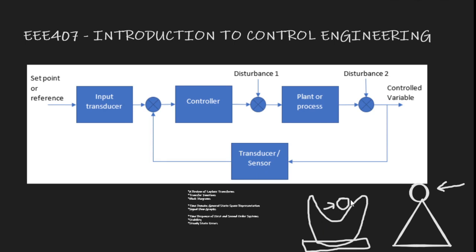It will roll to one side a bit, then it will come back down and then go back, and in the end it will settle in the center. So the amount of displacement you have will not be much. It's a bounded output. You supply a bounded input and you have a bounded output. This system we could say is stable.